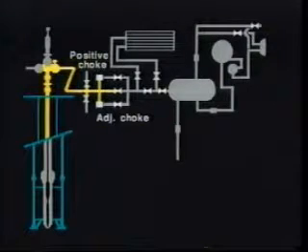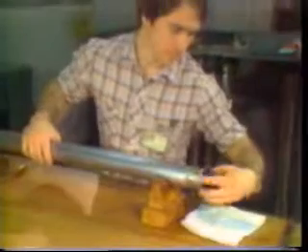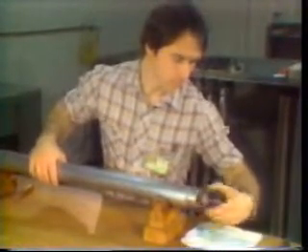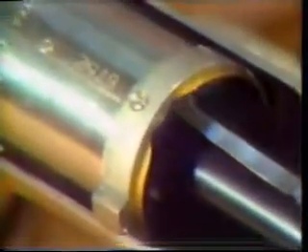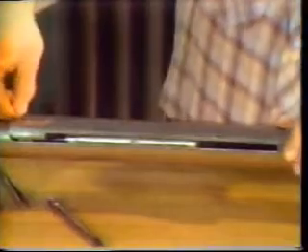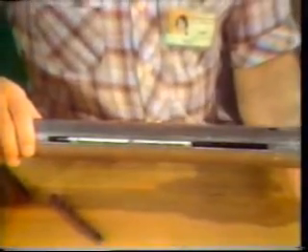Once the flow rate is controlled, we turn our attention to measuring pressures. There are 2 types of recording instruments used to record pressures during a well test: mechanical and electronic gauges. The pressure element of a mechanical gauge is normally of the multiple coil Bourdon tube type. Well fluid pressure is transmitted through a rubber diaphragm to fluid contained inside the Bourdon tube. Pressure increases cause the tube to uncoil. The rotation is transferred to a stylus which makes a mark, usually on a coated metal chart. The recording chart is moved vertically by a clock with the speed of movement along one axis of the chart dependent upon the clock selected. The rotation of the stylus in one direction by the Bourdon tube records pressures. The movement of the chart by the clock in the other direction records time. The relative motion of each yields a pressure time chart.